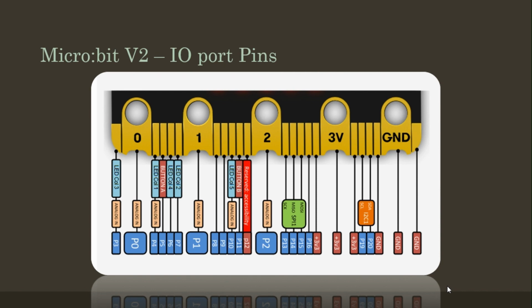an Arduino sketch. As Microbit was not originally supported on Arduino IDE, accessing the I/O pins can be confusing and frustrating for beginners. While information on the external I/O pins is available, finding information on Microbit to Arduino pin mapping for the internal I/Os can be challenging. Since the Microbit board comes with several onboard I/O devices, it is important to know the pin numbers of the internal I/O pins connected to these devices or sensors.